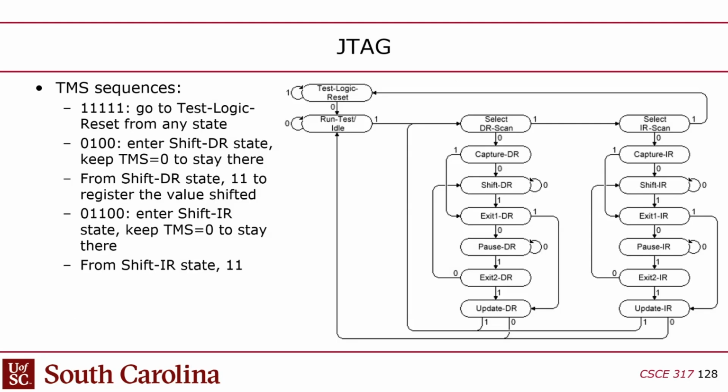Okay, let's see. One of the neat things about this state machine is that if you put 5 or more 1s in, you'll always go back to the test logic reset, no matter where you're coming from. So that's a good way to reset the system, even if you don't know what state it's in.